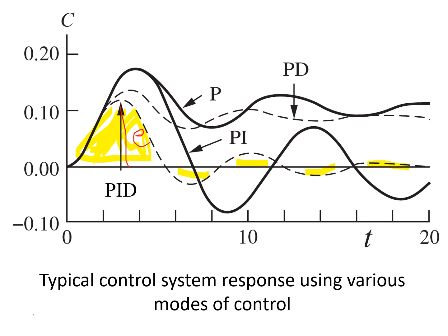So this is the way you are normally going to design your controller. Other than just using the straightforward controller tuning, you can also use this to decide, try different tunings and calculate the dynamic criteria and decide what is the best controller for you. Of course, you can do it easily in Simulink and on computers to make all this decision, using all the different criteria, not just one: IAE, ITAE, ISE, the offset criteria, the overshoot, the rise time. You can use all the criteria and make a decision.